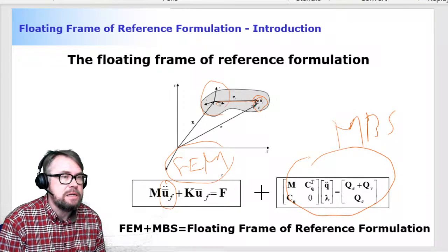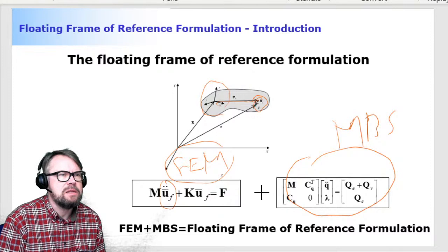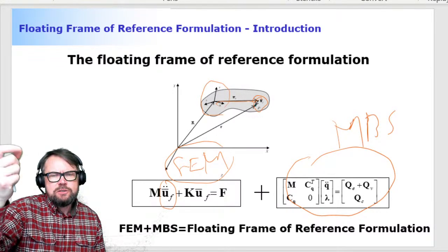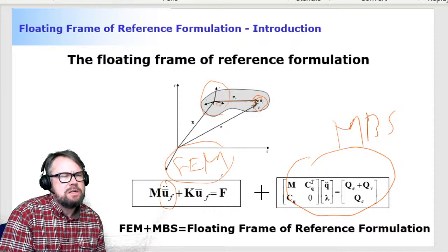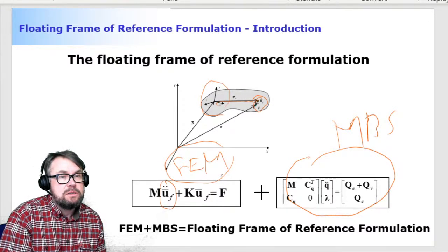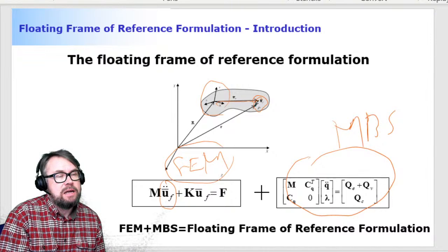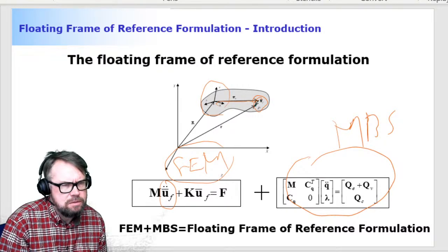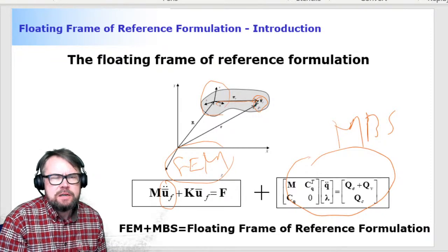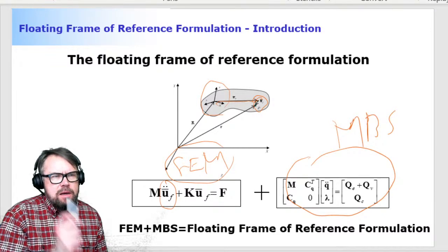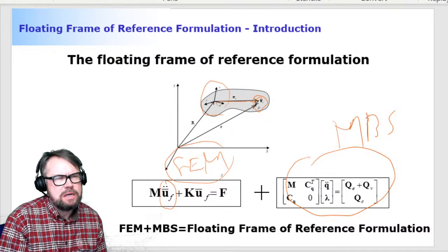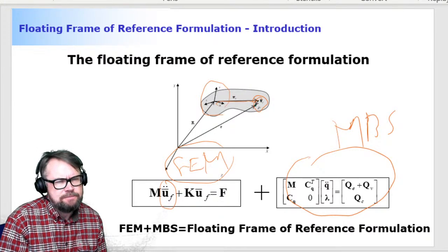And again, the idea in model reduction is that we're looking at the features of the structure, and we're picking up those features that we believe are the most important ones and ignoring the rest. It's like a magic thing that happens. We will lose a certain amount of accuracy, but not much. Because having 100,000 degrees of freedom means that the structure can deform in 100,000 different ways.